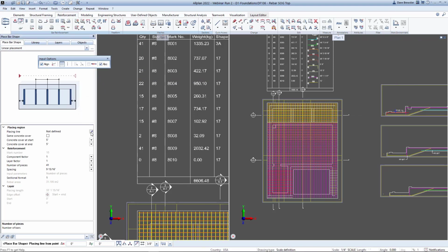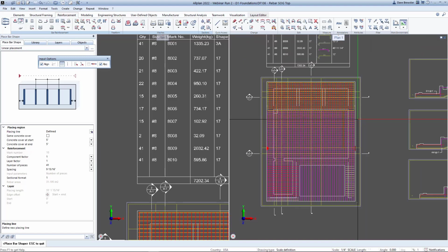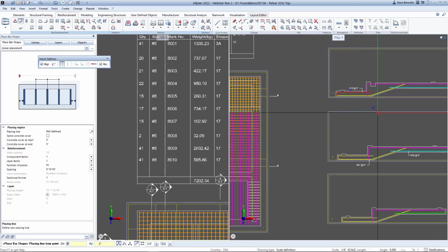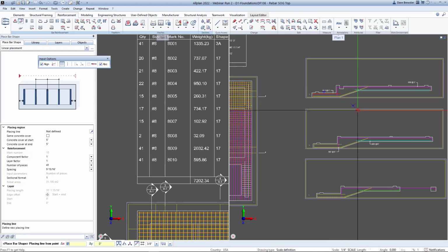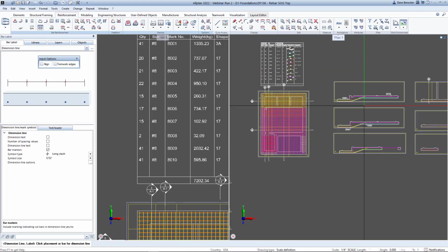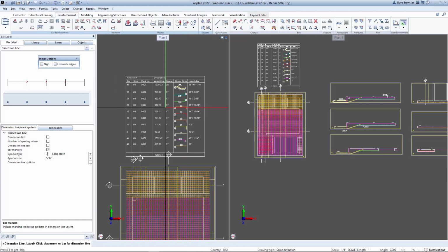Now I'm going to place that bottom bar that I've shaped. Do the same thing. This one here, I'm going to use the tool. You'll notice it picks up on the proper range, because of my last numbers I put in, where it's going to assume those as being your last numbers. And now I've quickly put these in as top bars.